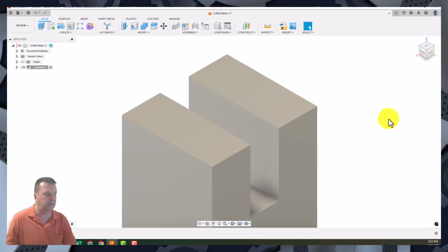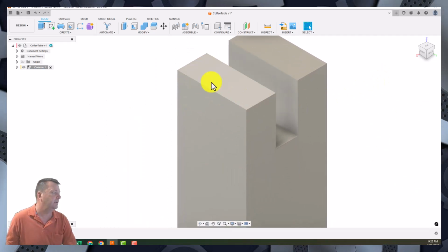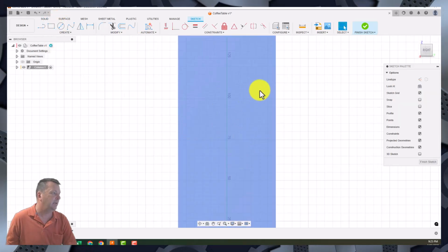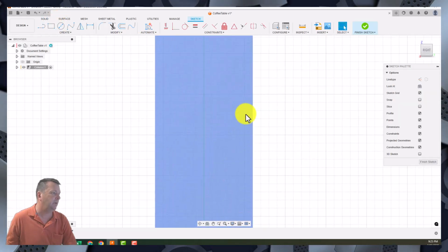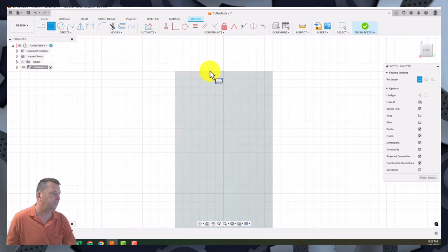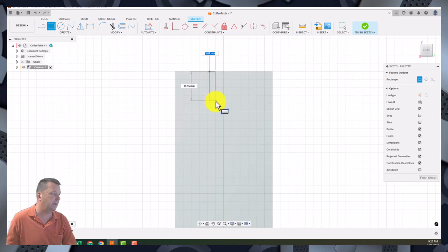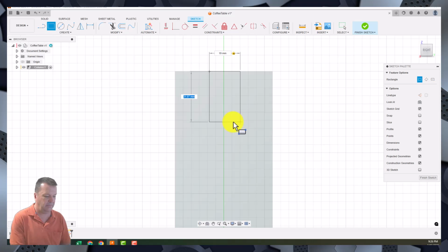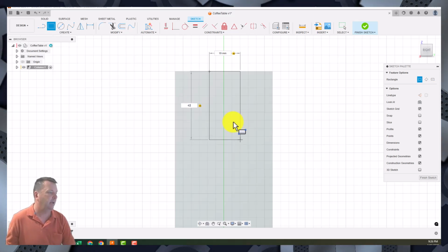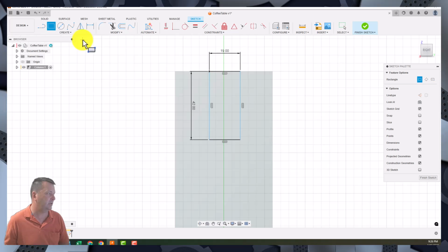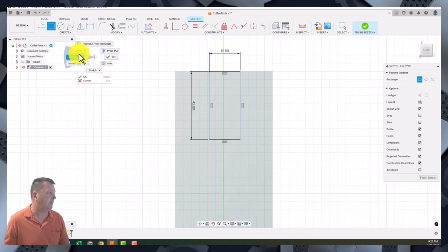Repeat this process on the second side. So we're going to go sketch again, click on this side. Again, bring your object to your column all the way down to the bottom. 2-point rectangle. You can see on the top there, you get that dashed line to show that it's recognizing it's at the top. Again, 19 tab 42. Actually, I'll show you, I'll escape out of that. Let's see, I'll actually go right click and go cancel.